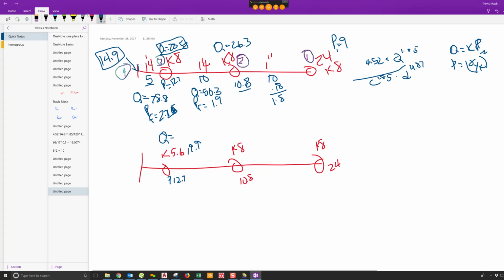As I'm going to throw another variable in here that I meant to put in, and I didn't put it in until the end. This one was covering, say it was covering 90 square foot instead of, these were all covering 120. Okay, 120. We're at a 0.2 density, but for whatever reason, due to walls or whatever, this one was covering 90 square feet. This head here was 90 square feet. Okay, so its Q min is 18 GPM. Do you follow that? 90 square foot times 0.2.